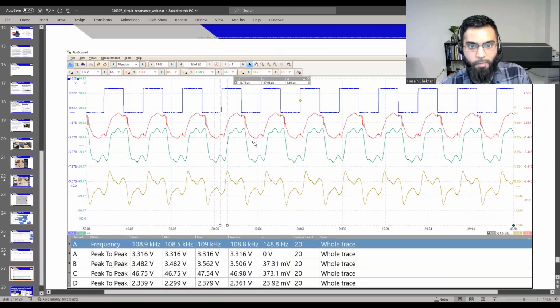Yeah, there's a lot of harmonics here. If you drove this with a sine wave, there would be no harmonics, so that could be done, using the chip that someone mentioned, or you can use other circuits to convert square waves into sine. However that fits your need, but the device works, and the current amplitude that is measured by the Arduino works. I'm going to describe that in a second too. So this is also kind of a square wave like output.